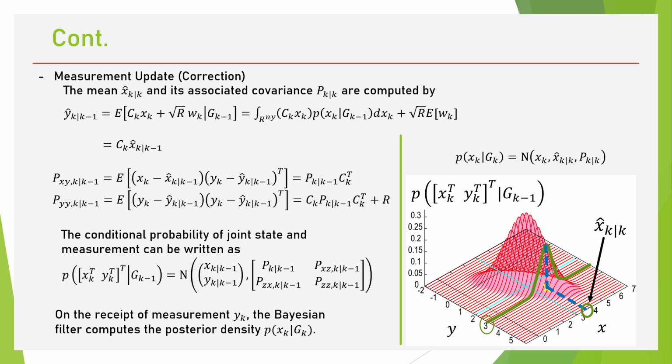And next, the measurement update. First, we compute the expectation of the output. If we have the expectation of h like this, and we know the model of the output, then we can compute the predicted output. It's actually simple: the model is c times x. So the expectation of y here is just c times the expectation of h, because the noise term is 0 as well if Gaussian.